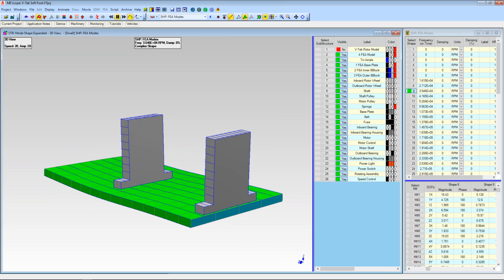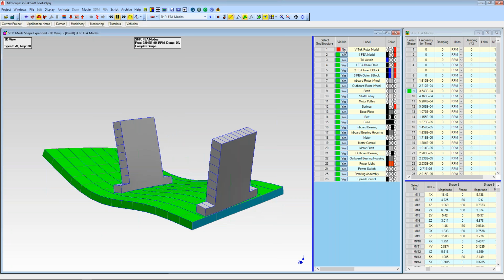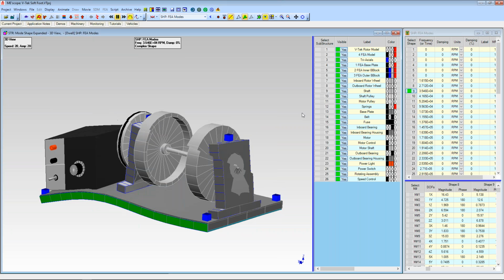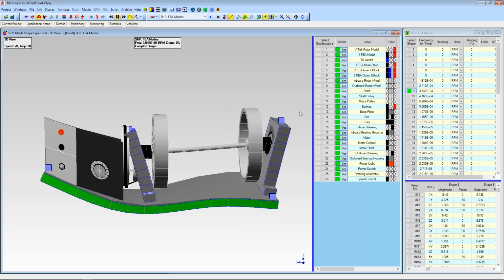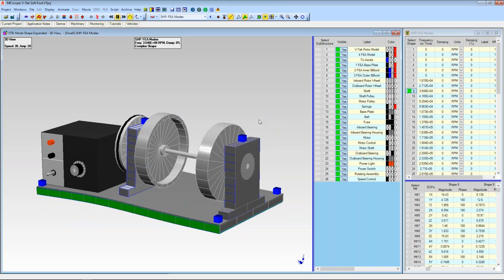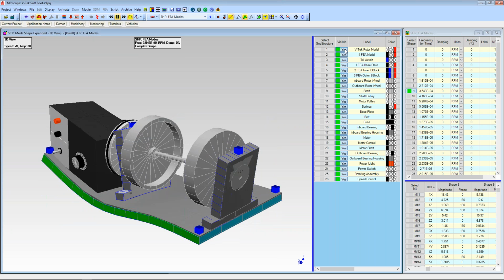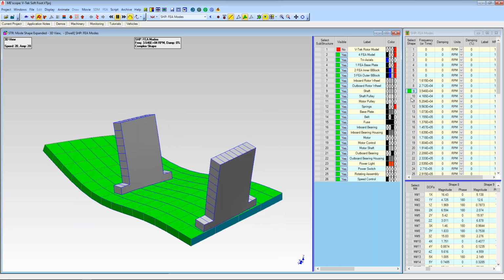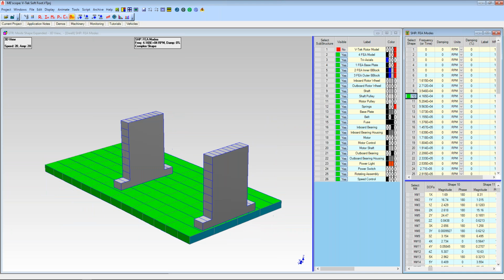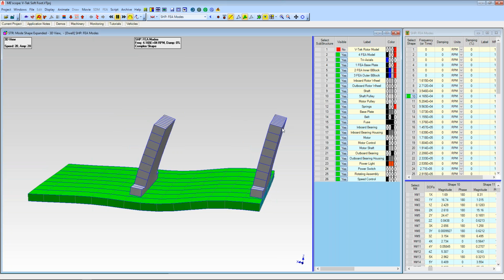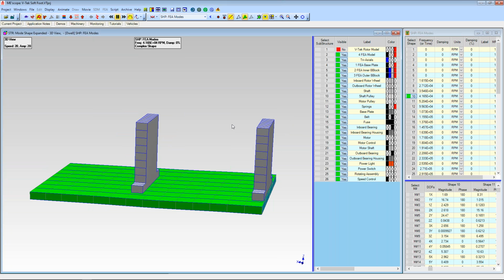Then, in order to animate the VTEC rotor model, we simply use our geometric interpolation. Now you can see it's quite exaggerated here, but this modal model is going to be the thing that we use, all these different mode shapes, and we used the first 10. Now if you use too many of them, then you're kind of curve fitting down into the details.